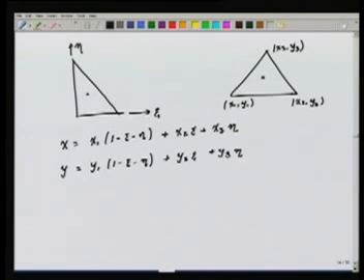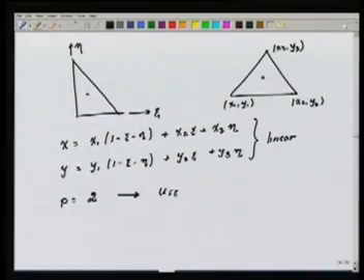So this was the linear map, while for the approximation of the finite element solution we used, let's say, p equal to 2. In terms of linear shape functions I could represent the mapping, while for the approximation, this is for the UFE, I could use p equal to 2, 3 and 4. We used it happily without any concern about all these things. That is what we mean by a subparametric approximation. That is, the shape functions at the element level which are used to represent the geometry are of a lower order as compared to the shape functions which are used to represent the finite element solution.